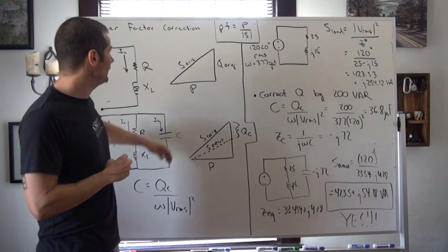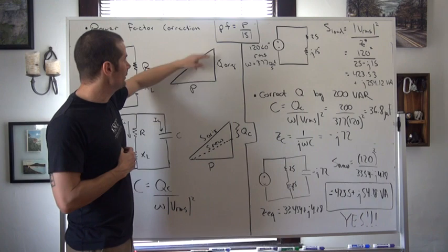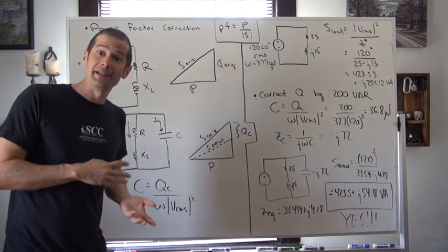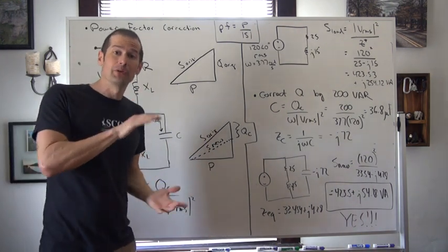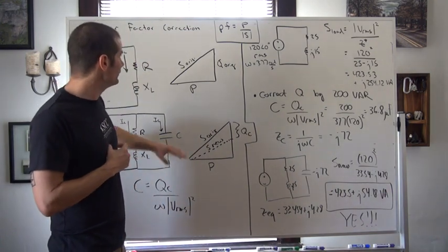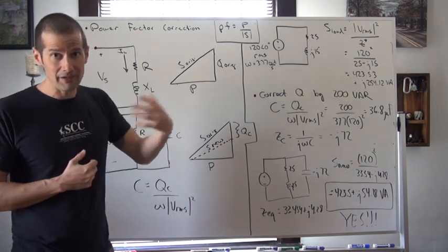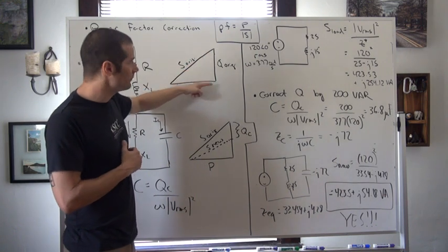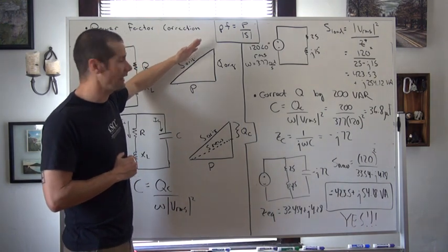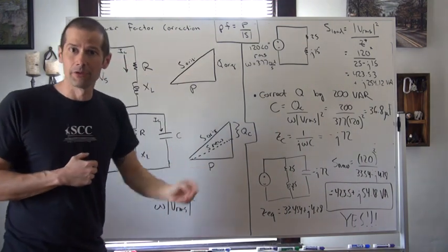And sometimes we may get too much inductance on that line. And essentially, as we raise that reactive power, we increase the amount of apparent power, or essentially the amplitude of the instantaneous power that's being generated. So if we want to get rid of some of that reactive power, in this case with mostly positive reactive power, we can introduce negative reactive power within that system that's going to cause that apparent power, that hypotenuse of the apparent power, to lower closer and closer down towards the real axis.